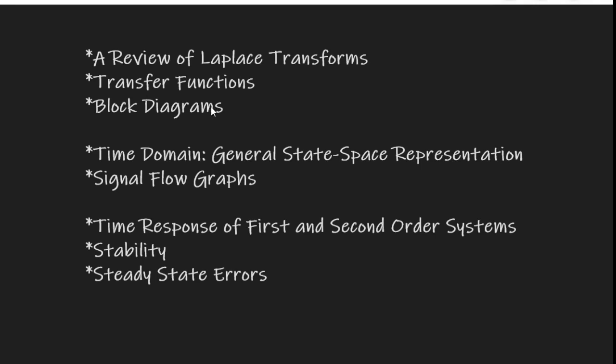Now, if we can represent our signal in the frequency domain using Laplace transforms, for example, let's assume our input signal is a sinusoidal signal, a sine wave. Then if we can take a Laplace transform of that sine wave and we check our outputs, we know the Laplace transform of the output. Simply divide that output by your input and you have the transfer function of a system.